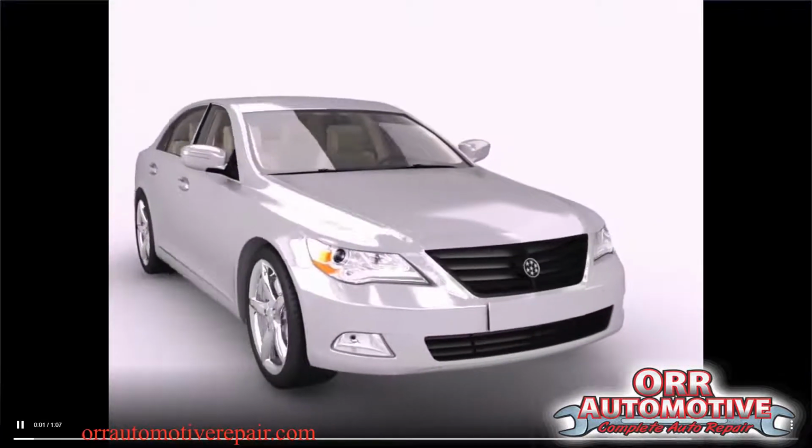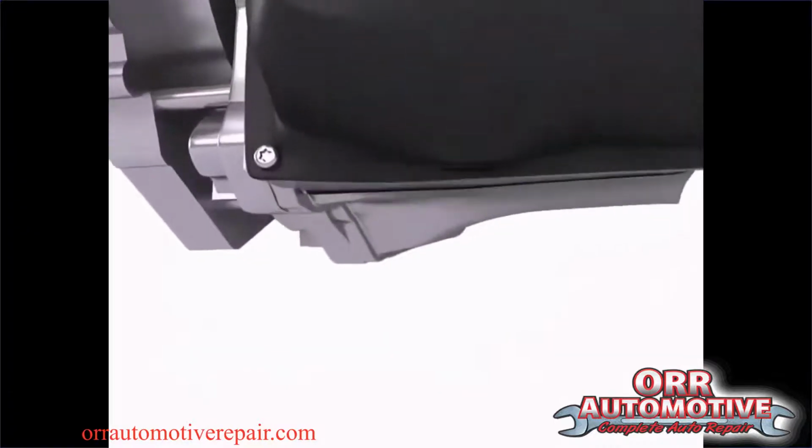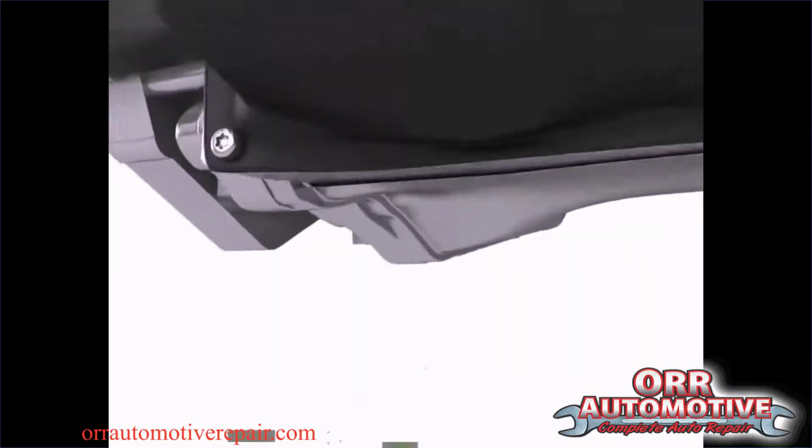The mechatronics unit inside the direct shift gearbox, or DSG, controls the flow of high-pressure hydraulic fluid to engage and disengage the clutches and select the correct gear. Before removing the mechatronics unit, the fluid is drained from the gearbox. The black plastic inner tube is used later to ensure the gearbox is refilled to the correct level.